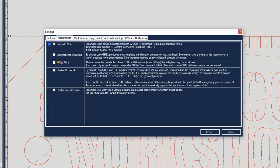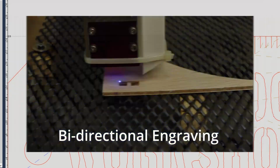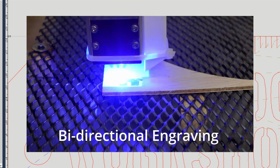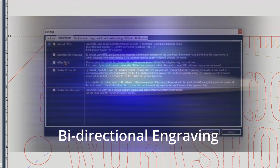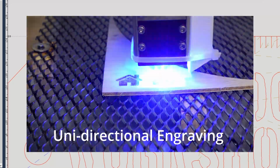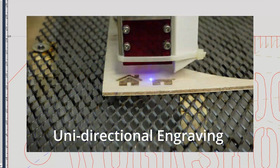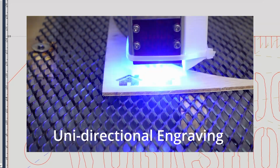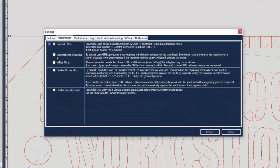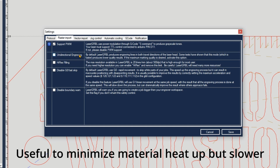Something else that you can change here is unidirectional engraving. By default it is not selected. That means that if you are engraving an image, for example, the laser will engrave in one direction and then also in the opposite direction. When it's scanning through your project, it's going back and forth, and in both directions it is engraving. If you don't want that for some particular reason, you can check that.